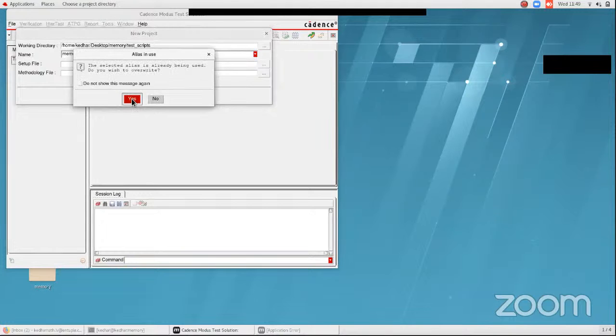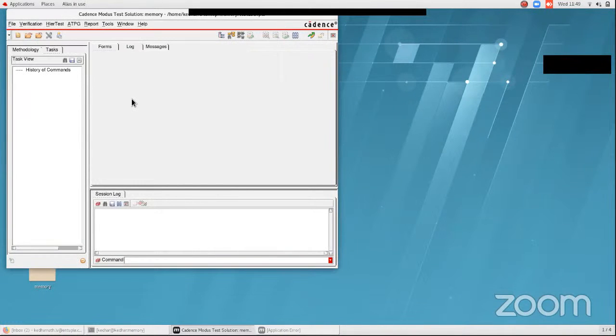So my workspace will be created under the column. In a similar way, first we will be building the model, and then we will be testing that model, and we will be creating a fault model, and then we are creating the ATPGs and writing the vectors. The same thing will be followed for any design procedure.